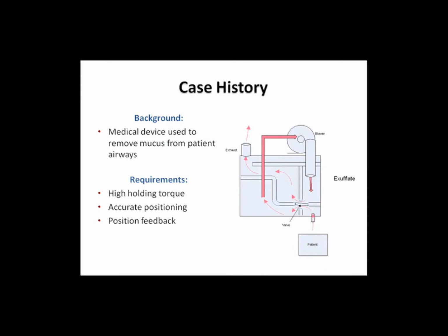Okay, so the valve moves at a certain 90 degrees, and you'll see a different flow. And in this example, the customer was able to successfully use an encoder and a stepper motor to be able to hold the position for the 2 cases, and you definitely don't want to have bleed off of flow while you're working with a patient. And so it gives them ultimate reliability. If there's something wrong with the system, it'll give them feedback. They can reset it, and it won't affect the patient at hand.